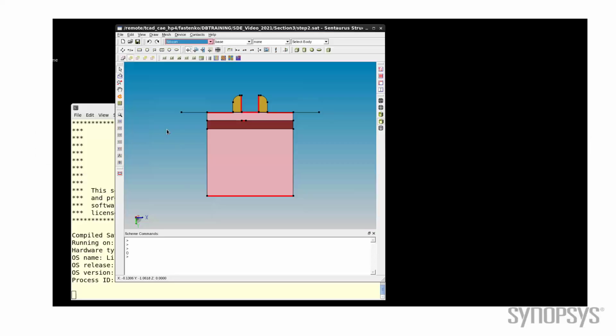In this video, we will use the structure of the 2D PDSOI device that we have created in the previous episodes, define mesh and strategies for the device, and generate mesh. Different device regions play different roles in determining the device performance, based on materials, doping levels and doping gradients, physical models, and so on. Therefore, meshing strategies for these regions are typically different. In this tutorial, we'll demonstrate the most common meshing strategies.